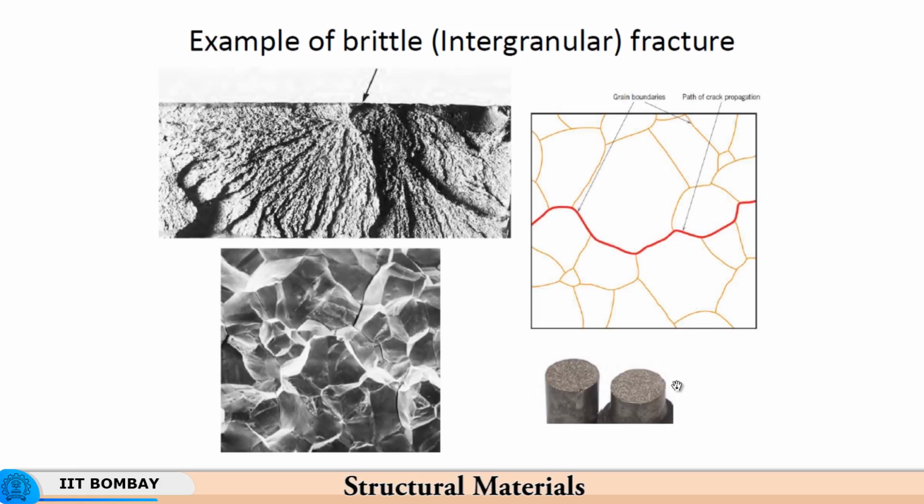So, now this is the intergranular failure taking place without any prior warning, without any plastic deformation taking place. So, that is why it is a brittle fracture. So, this brittle fracture is intergranular, it occurs all of a sudden, and the piece snaps into two parts.